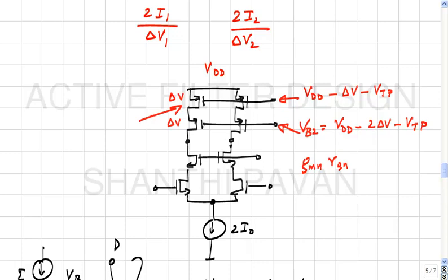In the gyrator, when we put the transconductors as a gyrator, what did we say? The input and output common mode must be the same, right? So do you think this is more difficult to do or easier to do? I mean, the cascode only helps if all the transistors are in saturation. You understand? Now what happens? Earlier, how low could this go? You had one transistor, so whatever, Vt by 2 was the maximum each node could swing. Now, what happens?